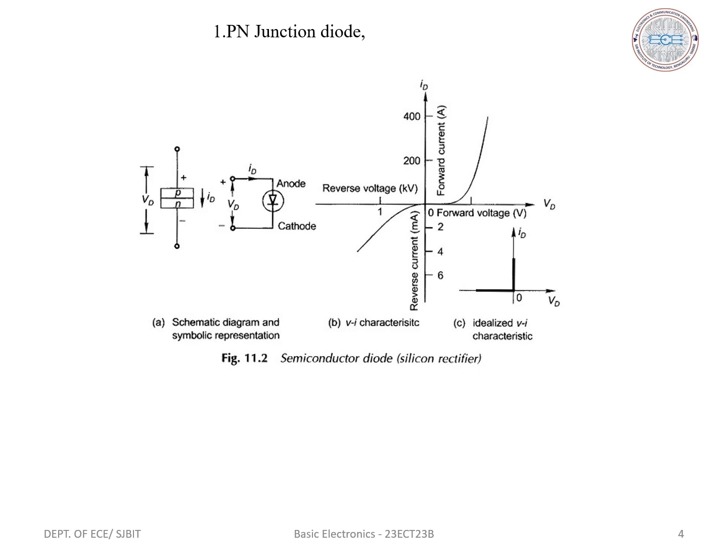So next we'll see how the reverse bias will operate. When a diode is reverse biased, holes in the P region are attracted towards the negative terminal of the supply and electrons on the N side are attracted towards the positive terminal of the supply. Due to movement of electrons and holes away from the junction, the width of the depletion region increases as shown in the figure. This happens due to the creation of a larger number of positive and negative immobile ions.